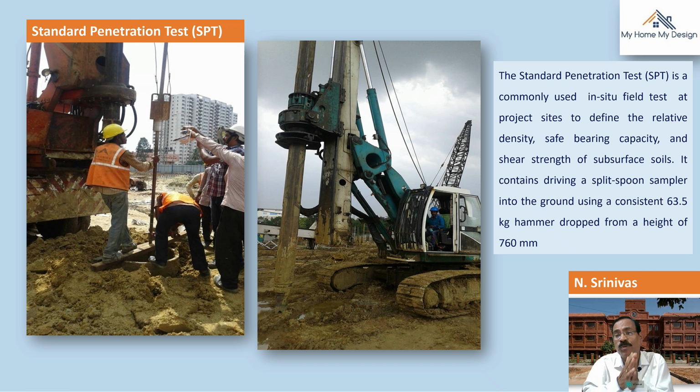This test gives an N value, the standard penetration value, based on the number of blows. The strength that is determined is the SBC, the safe bearing capacity of the soil. With the help of that result, we can decide what type of foundation is required, either a shallow foundation, deep foundation, or pile foundation. It can be determined with the help of this.